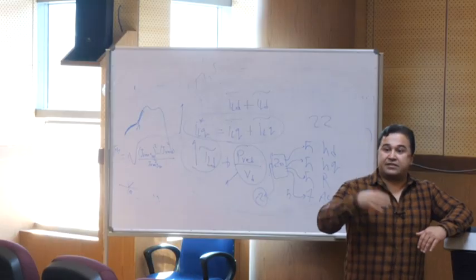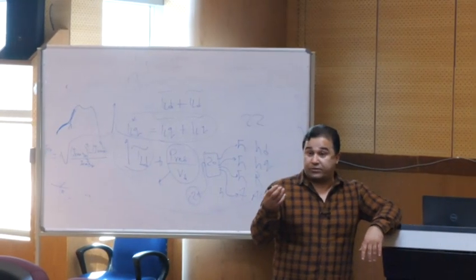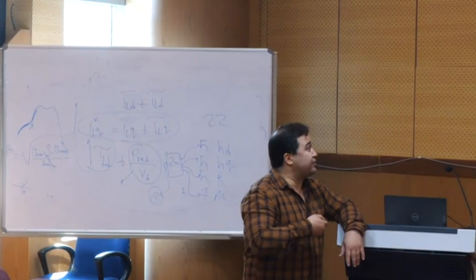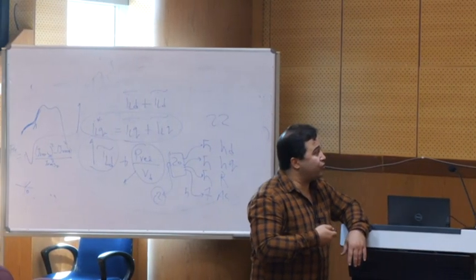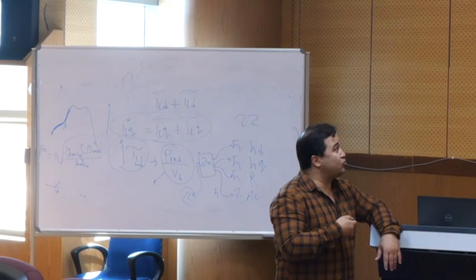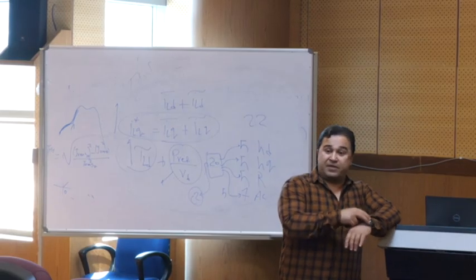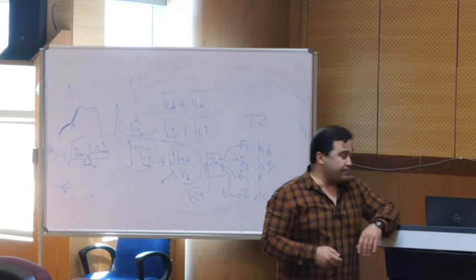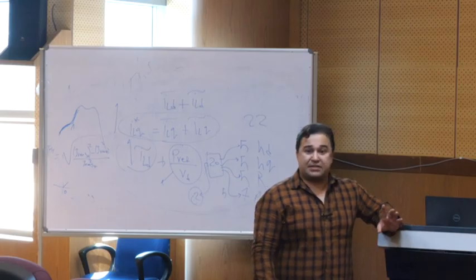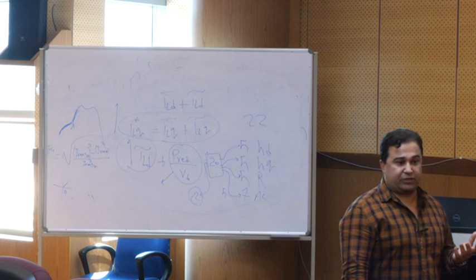And if we increase the value of the THD, it means that it is more non-linear. So this is, for example, THD is 4.18%, but this is 22.97%. So it means that the system is too non-linear. So in grid code it is said that,